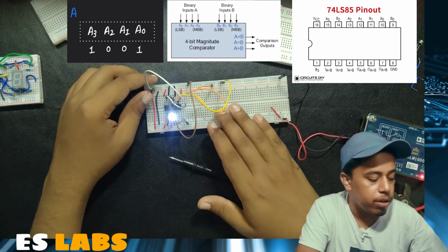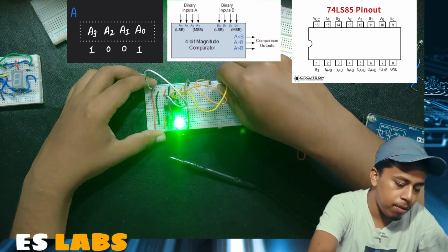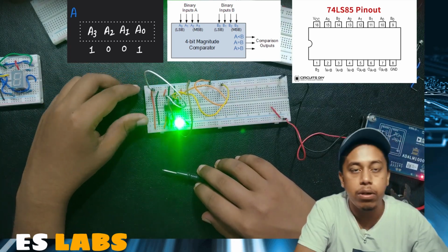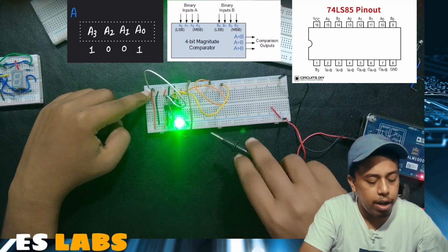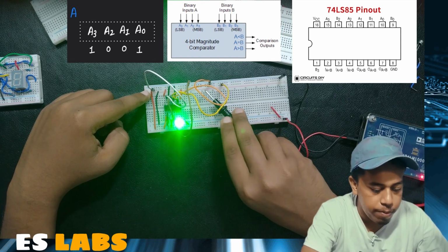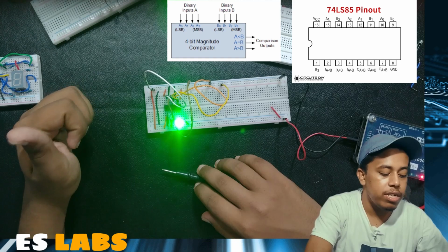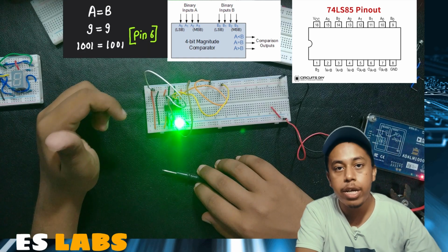Again, we change the input of A. I have given the input of A as 1001, in which A3 is connected to 1, A2 is connected to 0, A1 is connected to 0, and A0 is connected again to 1. We can see that the LED at pin 6 is glowing, representing that A is equal to B.